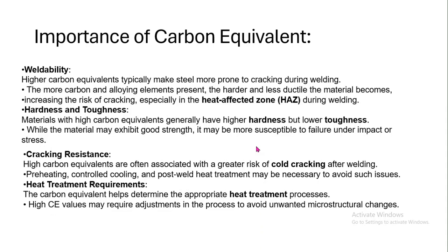How does the carbon equivalent value influence the material? First, it will affect the vulnerability. If the carbon equivalent value is higher, specifically in steel, it is more prone to cracking during welding. So we can face cracking issues during welding because of the carbon equivalent value.